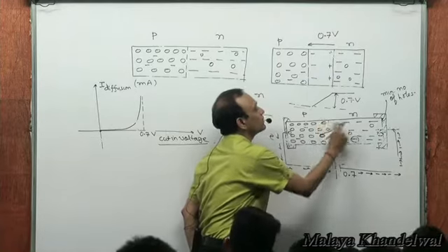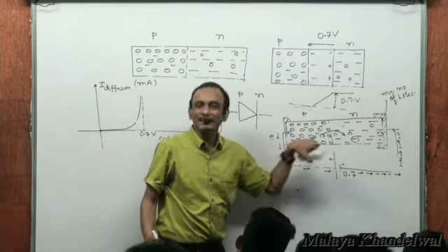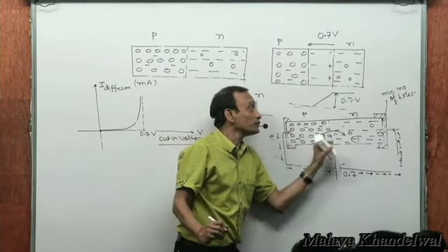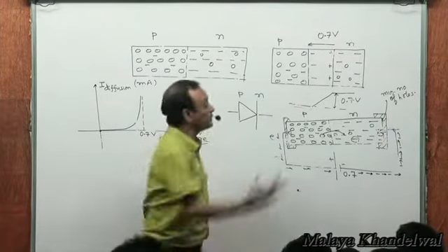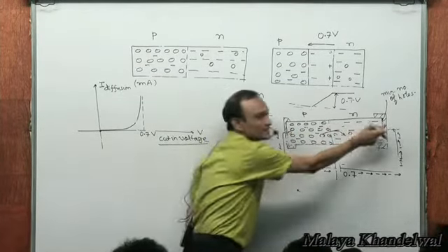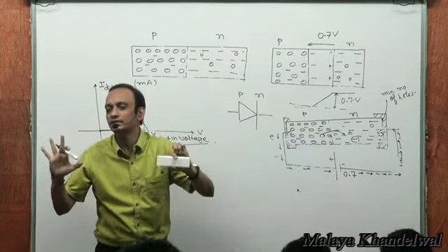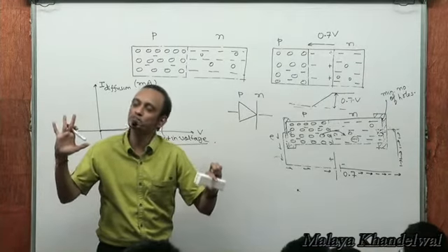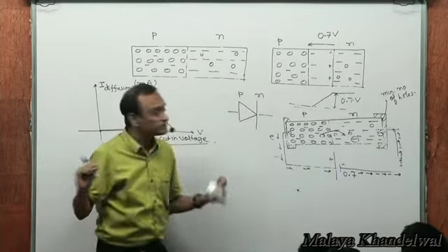So these electrons will come down here. Now these electrons are surrounded by a majority of holes, and these electrons will get consumed. So again, the difference in concentration levels of electrons in this region and this region would be reasonably maintained. And if some electron moves to this region, then a new electron will be created in this region. It'll get consumed by a hole. The difference in hole and electron concentrations in the two regions is going to be preserved, not killing the diffusion current, right?